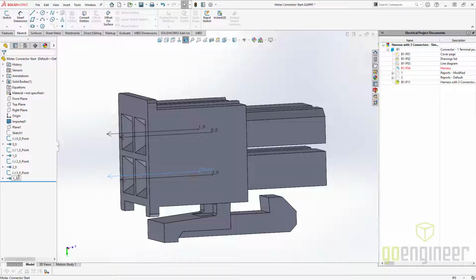So I actually have to rename that as 3_0, and then Electrical 3D will pay attention to it. If we don't have that, and I'll do a rebuild here just so that'll show up on the screen, if I don't have it named that way, it doesn't know that it's on the third. Well, it's the fourth one because we start counting at 0, right? So it's the fourth circuit in the set, labeled 3_0, 0 being the terminal number there.